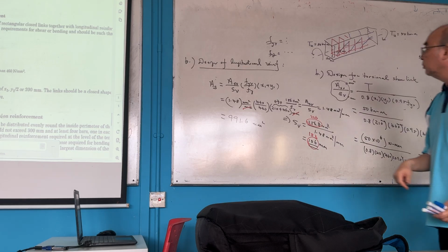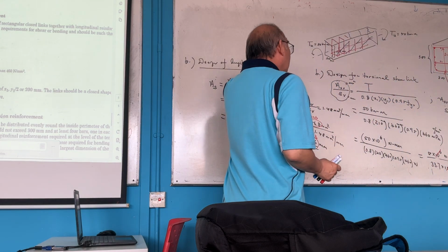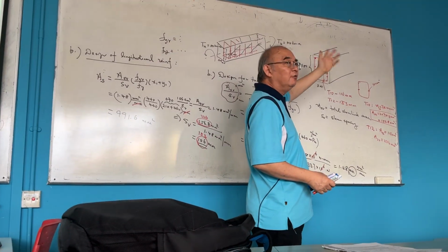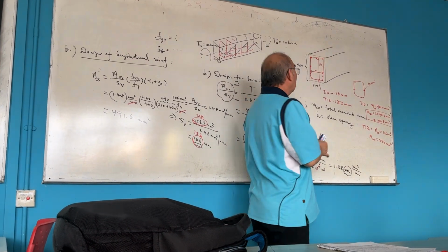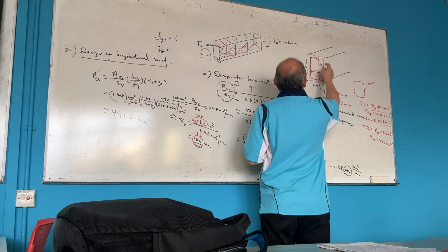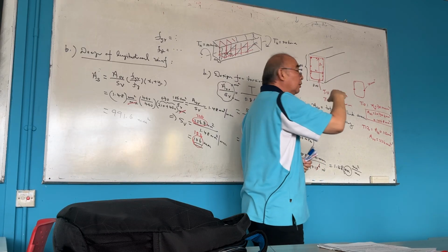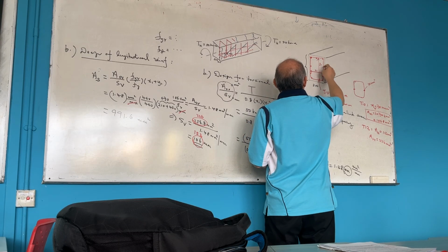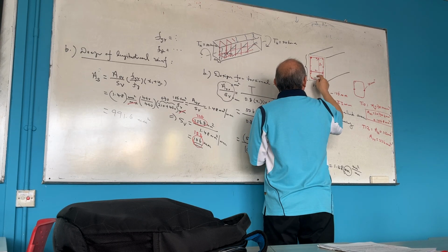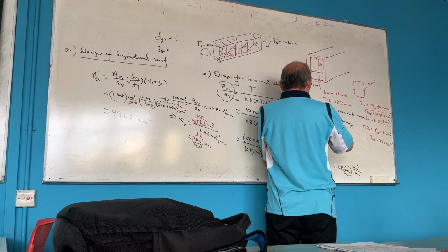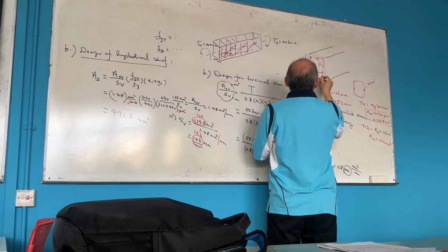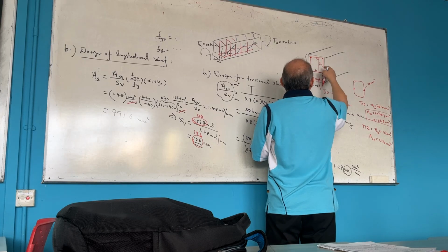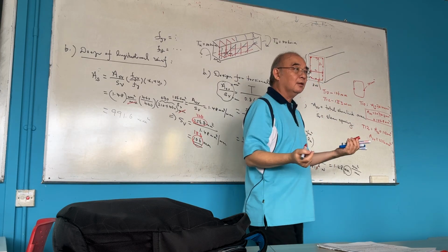Now, normally our longitudinal bars we need to distribute evenly. So here, first we have 1, 2, 3, 4, four corners. Then we have 5, 6, 7, 8, 9. So normally what you do is you make it 10 so it is distributed evenly. So we use 10.